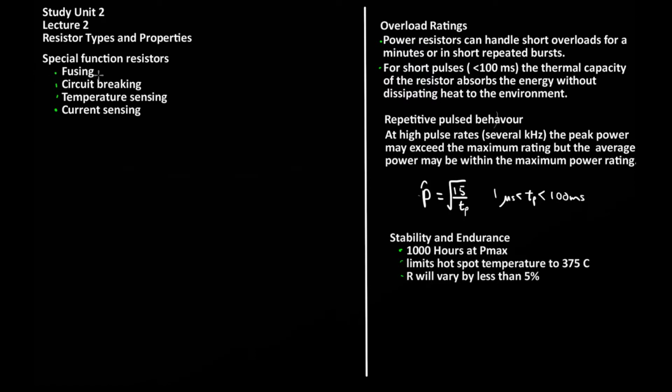What this means is, once a certain power dissipation has been exceeded, then the resistance of the resistor will increase by parts of the resistor literally fusing apart. This means that the rated power dissipation of the resistor will actually increase, but the resistance will also have increased.